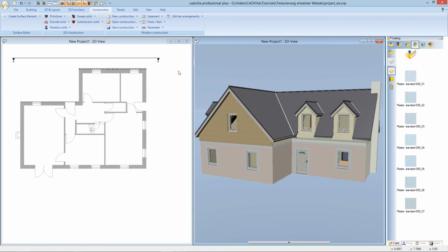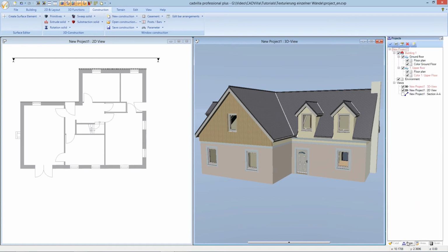Finally, I show you now the reason why we have created layers for each floor. In our case, we can now deselect the textures for each floor very easy. If we would have created all textures on the ground floor layer and we would hide the first upper floor, the textures would get still displayed. So please always create a layer for each floor on which you create textures.